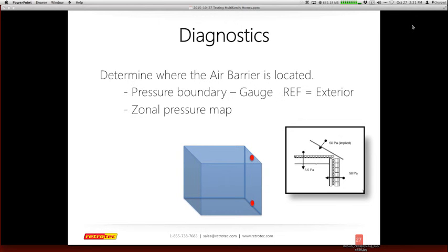Sometimes you can just go down to the stairwell and prop a door open, and now I actually have access to outside, versus keeping the door closed and understanding some of the pressure issues that happen when I have an enclosed area that's 3, 4, 5, 25 stories tall, actually affecting pressures inside the unit itself, which also impact the common hallways and impact my individual units.